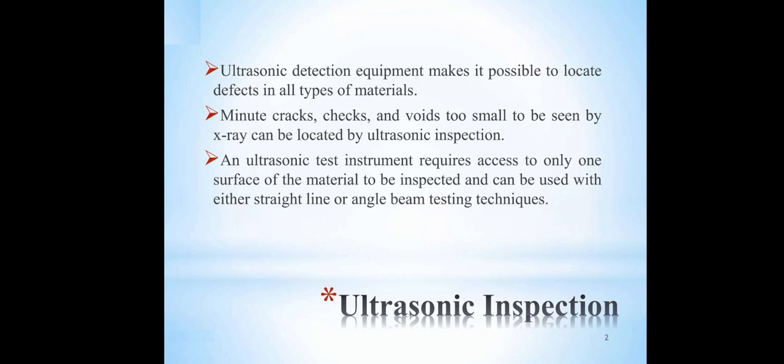In ultrasonic testing, high frequency sound energy is used to identify surface and subsurface discontinuities. Ultrasonic detection equipment makes it possible to locate defects in all types of material. Minute cracks, checks and voids too small to be seen by X-rays can be located by ultrasonic inspection.